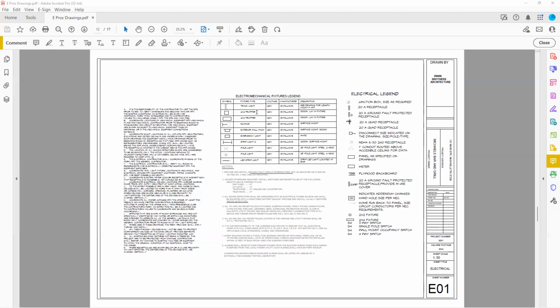That's going to help give you some visualization of what it is you're installing and help you to plan ahead. It's going to tell you what the voltage is. Some of these commercial jobs, you have different voltages coming from different panels. So here we can see that on the schedule, everything's at 120, which is fine. A lot of fixtures have multi-tap options on them to where you could wire them up for 120 or 277 or different voltages. The manufacturer and the description of the light.